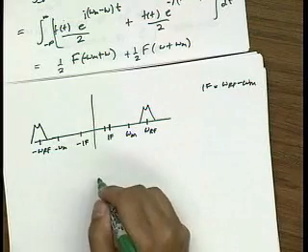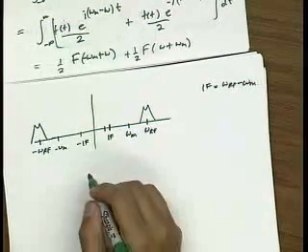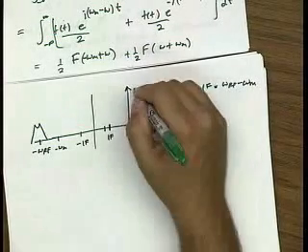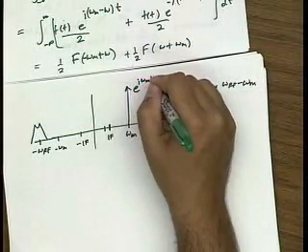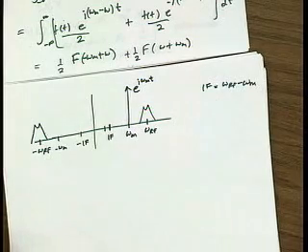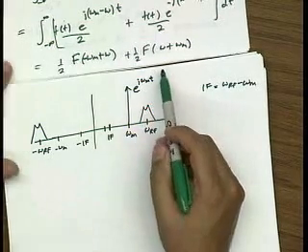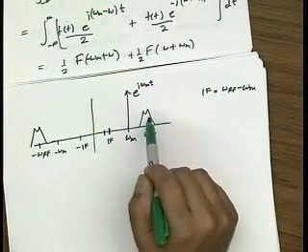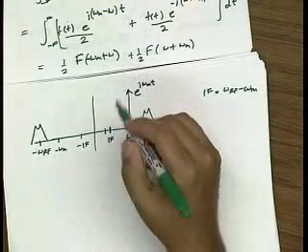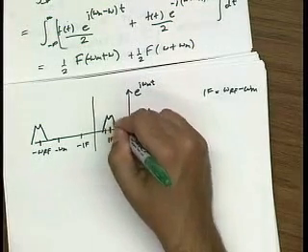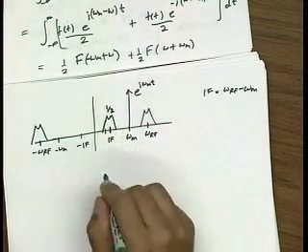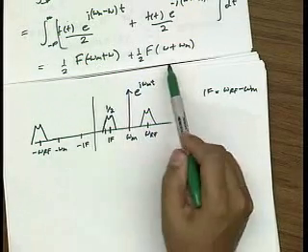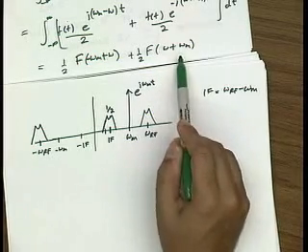Okay. Now, if I simply were to multiply by this term, which is e to the j omega m t, then according to this calculation, we can see that I will get two terms. First of all, this term with a factor of 1/2, which corresponds to omega minus omega m. I will get this term, which is omega plus omega m.